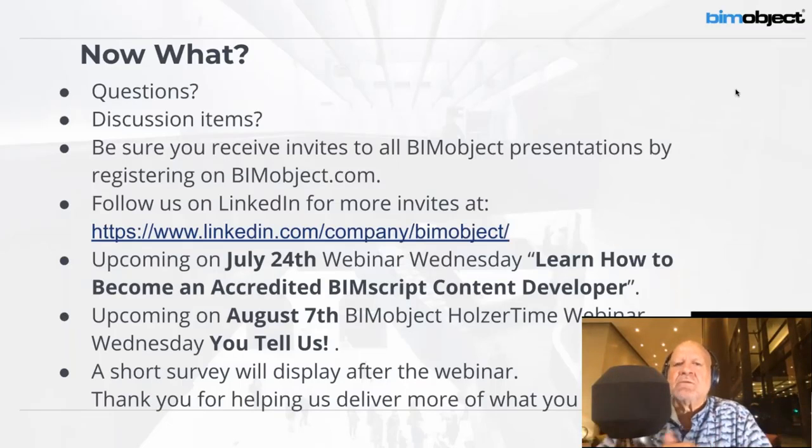So at BIM Object, we have our property sets, which we externalize. And this is one of the reasons all of our content has a call to home function, where essentially a GUID or an identifier lets, 5 years down the road, those external property sets of maybe the STC ratings or flame spread or any of this other metadata, COBie data, be accessed independently of, let's call it, the model file.